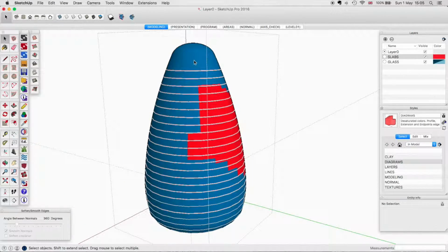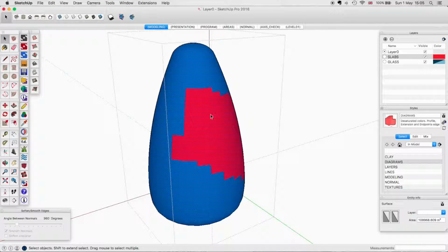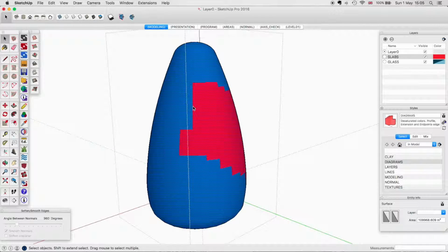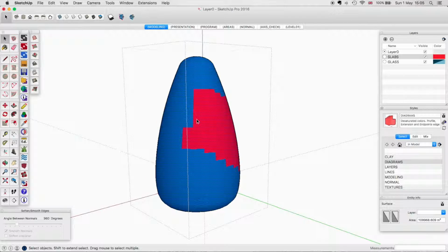And the wrong thing is that in the shell of your tower, you're using two different layers for different parts of your glazing system. In some cases, it's probably something you want to do, but if you want to keep all the glass elements of a tower in one layer, you should keep them in one layer.